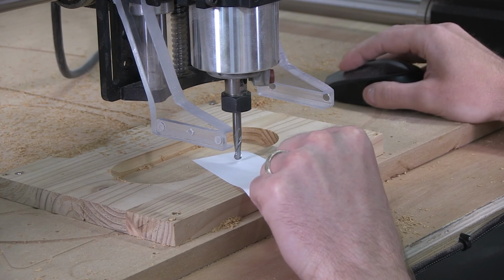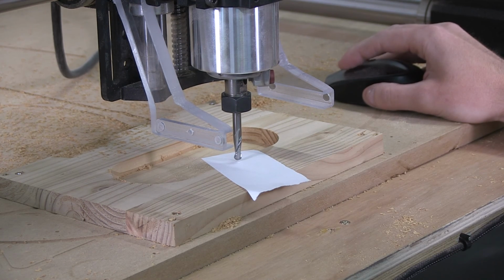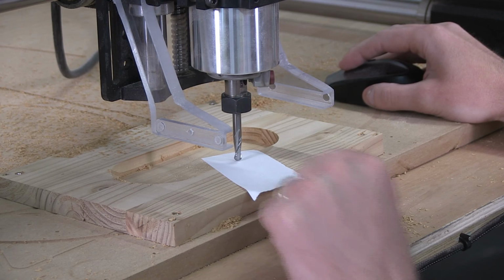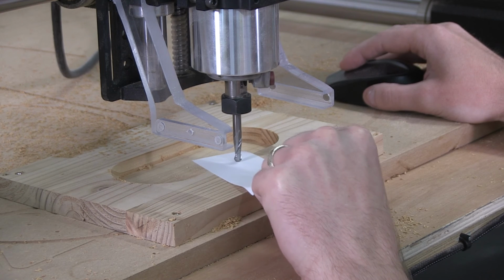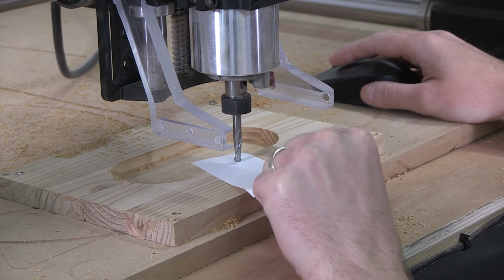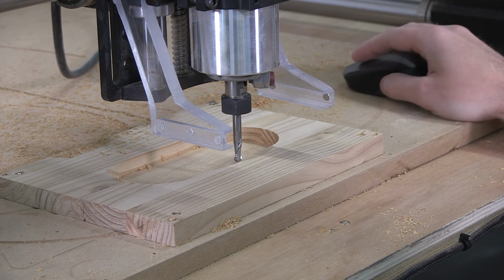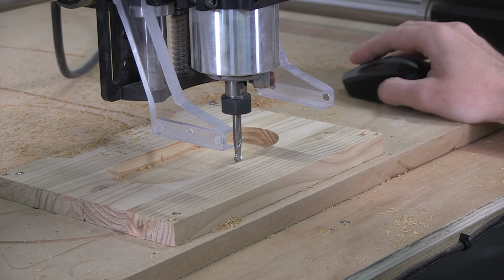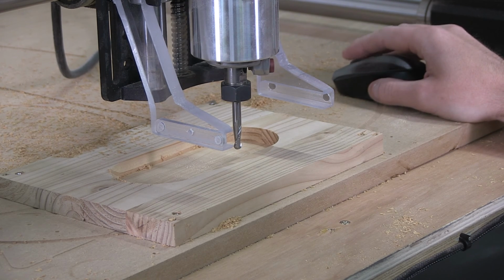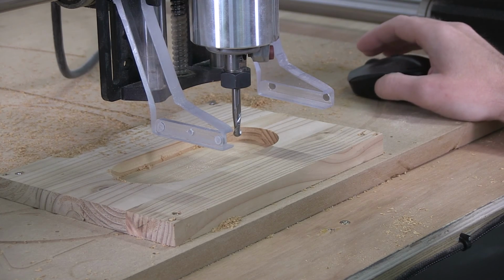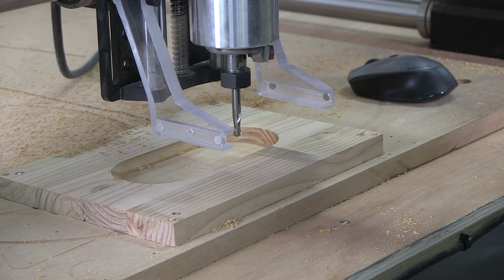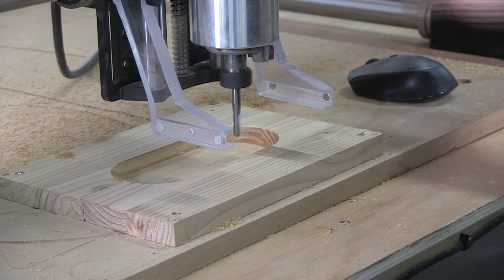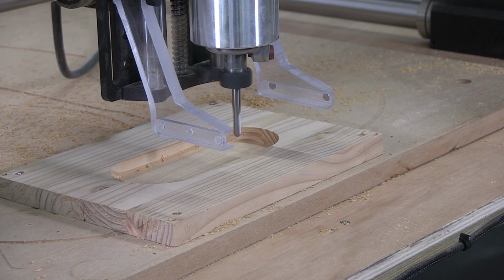So I've changed tools, moved the ball nose over, and then I'm dropping this down, setting up my Z height. And when I actually touch on the piece of paper, what I'm doing is bringing it back up by about 10 thou. The reason that I'm doing this is that I purely just don't want this to go too deep. I want this to be a nice feathered finish on there. I want it to blend in nicely. If I have to do the ball nose toolpath again, I can just drop that Z height down and rerun the toolpath. It's not really going to be a problem because it's quite a short toolpath.